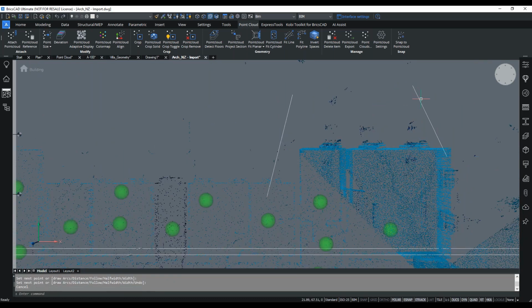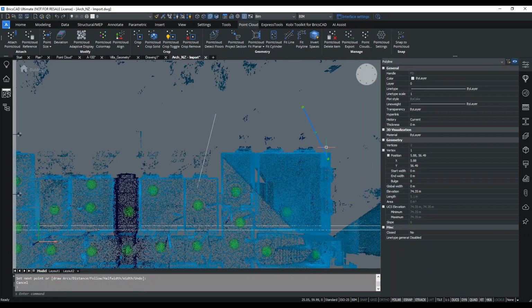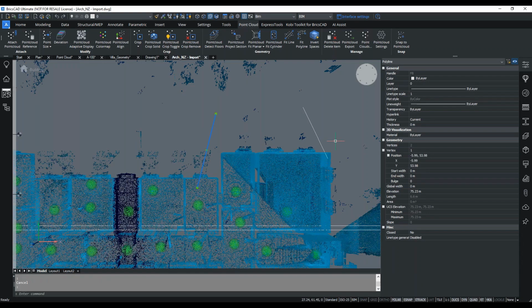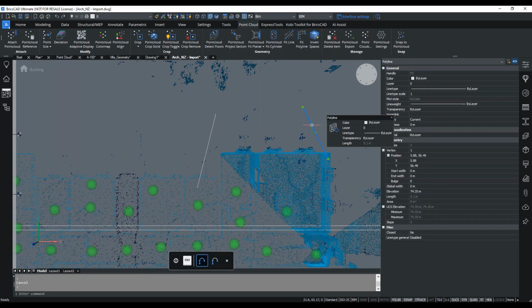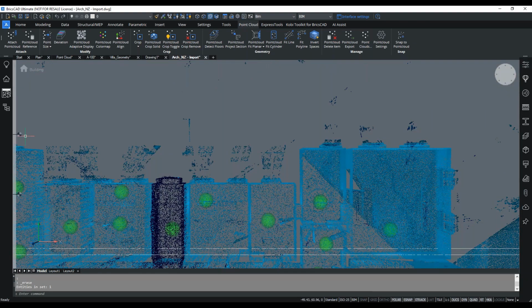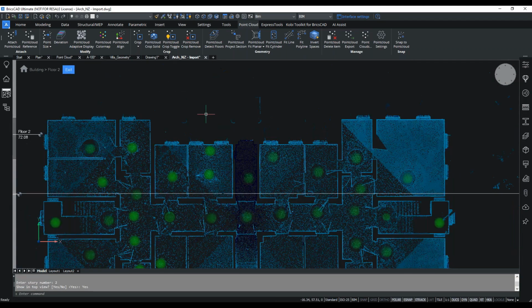These two lines have got different elevations. So this one's got an elevation of 74.35, and this one's got an elevation of 75.23. Because we're obviously snapping to various random point clouds, random Z elevations on our area. And what's interesting here is when you're on this view, the Z value is controlled by the floor elevation.